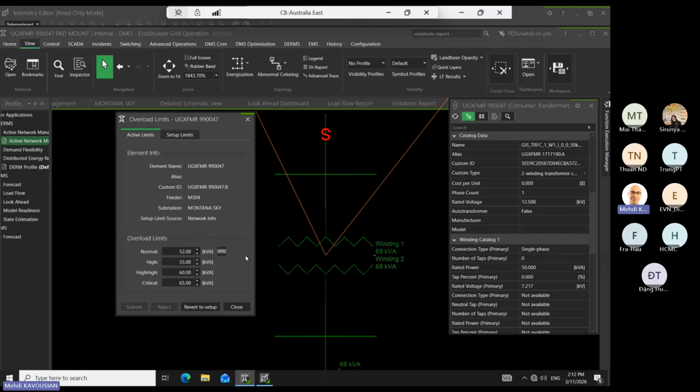And also for on and off, do you know what on and off means? Like oil. Some of these distribution transformers, but in the HV and MV, you have a fan for the transformer to make it colder, or you have oil, or you have air, those types of things. You can go beyond the limit of that. So let's say it's 5 megawatts, you can go to 6 megawatts for a limited time. So you can use this one to play with that.